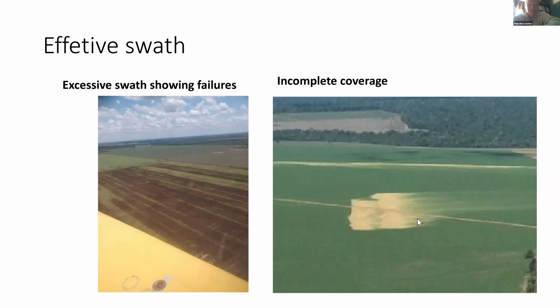This aircraft had actually been calibrated using the string deposition system, which determined the specific swath for the aircraft, and you can see it's all streaked. The photographs in the middle and the right, that is glyphosate as part of a test, applying glyphosate at different flying heights to see the true swath. We must conduct the flight pattern test with the chemical, not with water. Please, we have had multiple failures because of this.